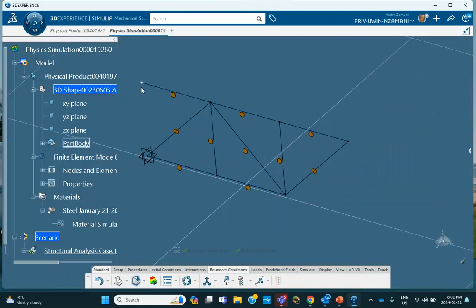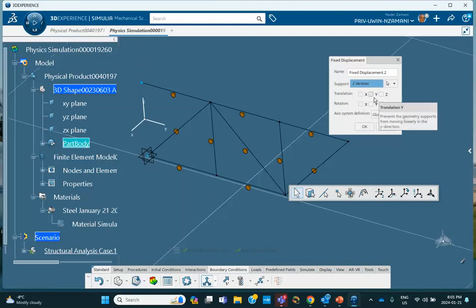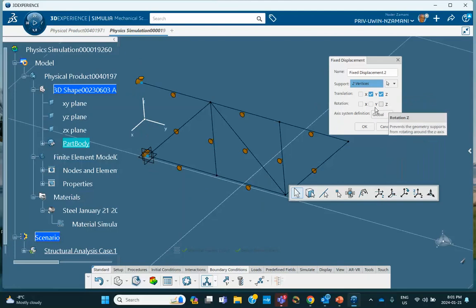These two endpoints, and it's very important that you do not put the restraint or the boundary condition on the points, put it on the vertices. So this last one, this point, and that point, okay, do not also move in the direction y and z because these are pins, okay? So no displacement direction y and z. Now, rotations are not important because these are truss elements.